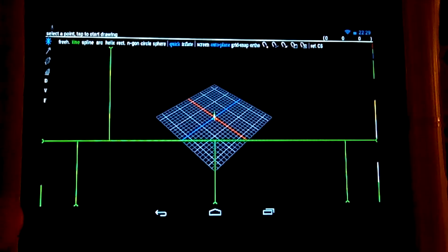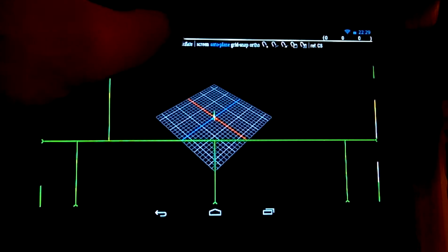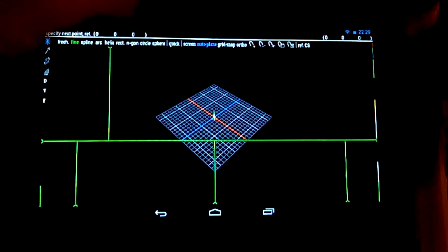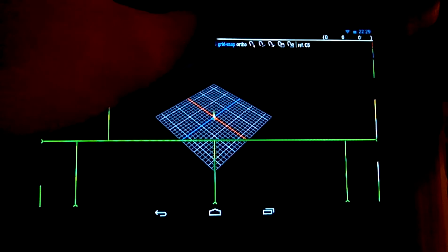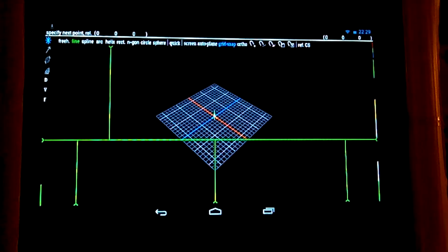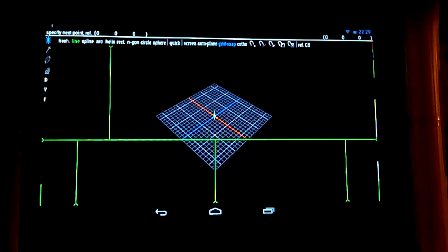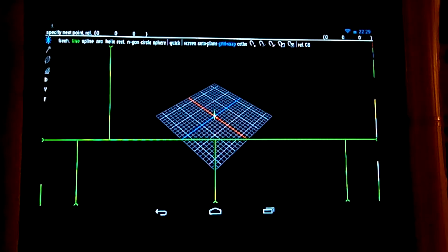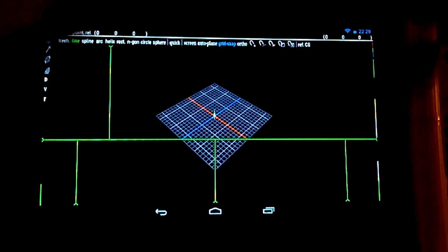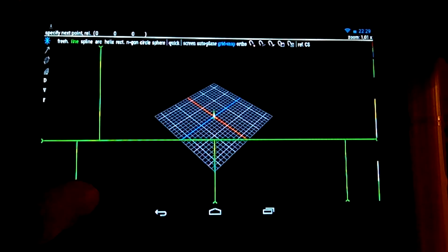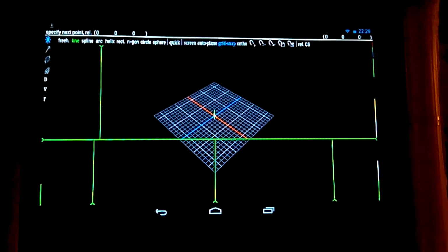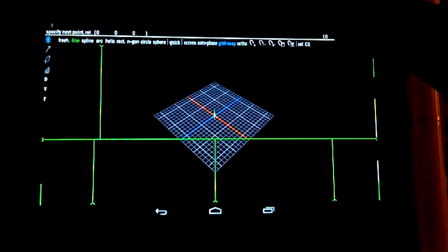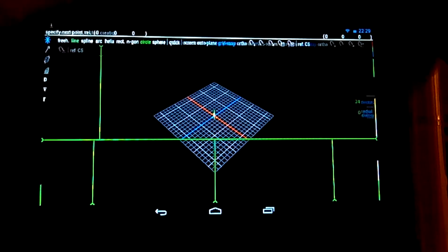Okay, I usually deselect Quick immediately, and activate grid snap and deselect autoplane. Quick is a very good way to make things more complicated. Okay, just adjusting the screen. Okay, perfect. So I said I'm starting with a cylinder, so I tap circle.